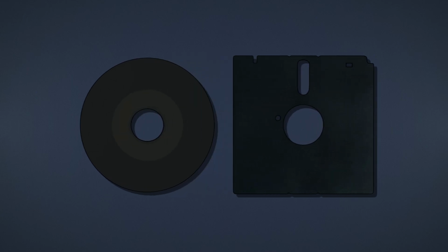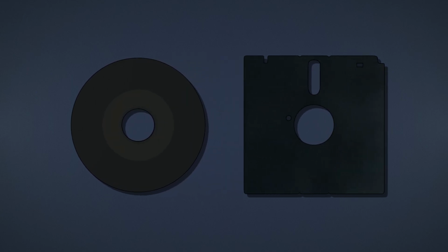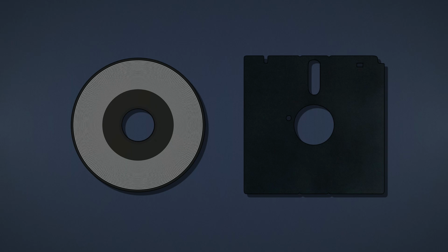Anyway, finally we have the floppy disk. Inside a floppy disk is a thin disc-shaped sheet that can store magnetic states. The difference to our hard disk drive is that the floppy can't actually rotate the disk by itself. It needs a floppy disk drive to do it for it. That's why there's a hole in the middle. This is where the drive holds onto the disk to spin it. And again, like the hard disk drive, the disk has multiple tracks of data that can be written to. And these tracks are also divided into sectors, which again is oversimplified in this visualization. There are many more of them.